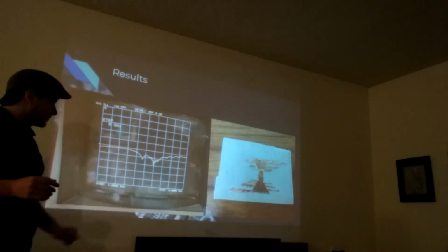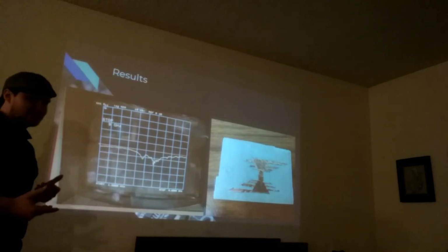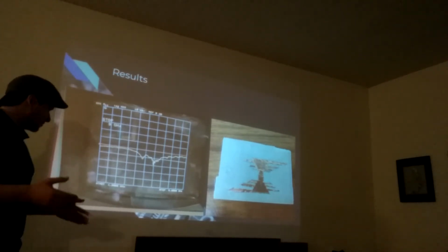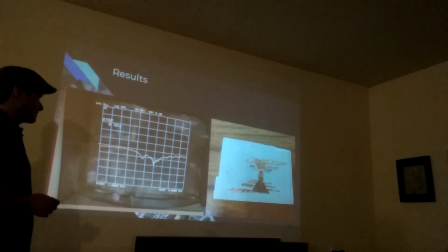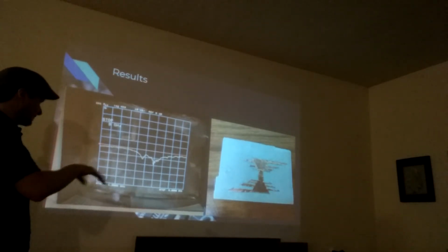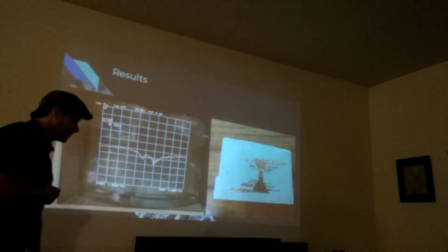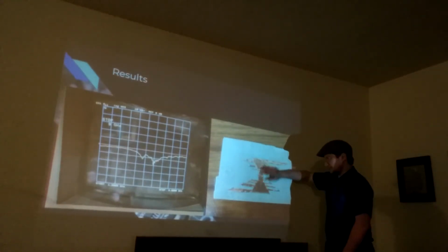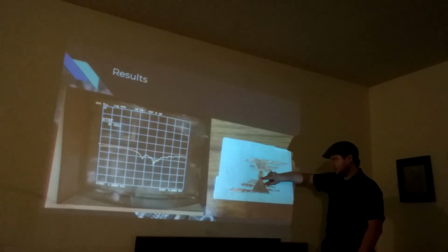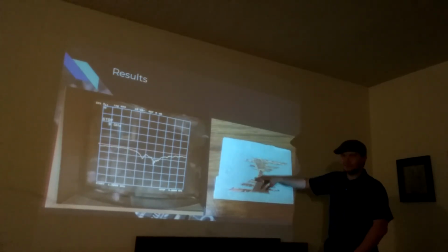And this was okay, but it didn't meet the design criteria that I was going for. It didn't meet a nice flat reflection coefficient for several frequencies that I was going for. So what I did is I disconnected the two different sides, this side and this side, and I used the probe such that the probe feed was connecting right here and the negative side of the probe was connecting right here, and these two are disconnected like a dipole.